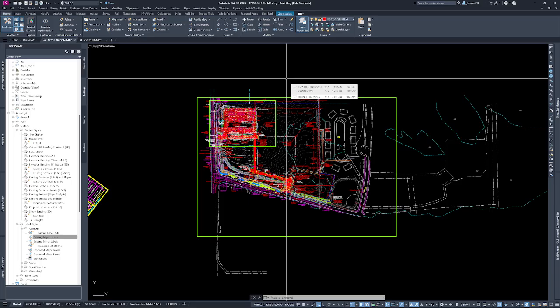Now, if you brought that surface into every single drawing, all the drawings would run slow. It's just not necessary to have all that extra information. But with the data reference, you can simplify what you want to see. You can draw borders, you can manipulate that so that you're only showing the area that you really need. If this is something that might be of interest, especially for environmental, we can look into it.